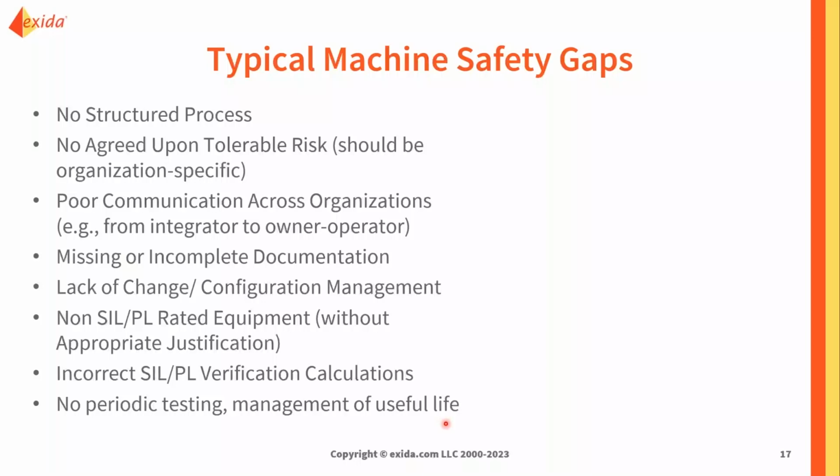And a lot of times those are the pieces of fine print that often get missed. And again, you may have companies running with something that they expect to be perfectly safe, where the safety function has failed and has been failed for years and had never really been tested. They didn't understand that it needed to be periodically moved or jogged to make sure that those hydraulic components were still working.